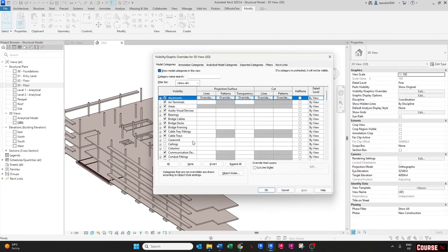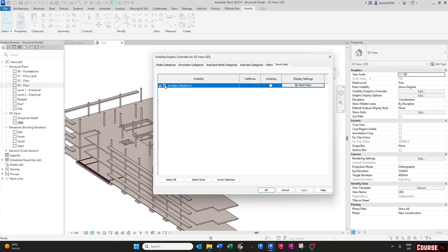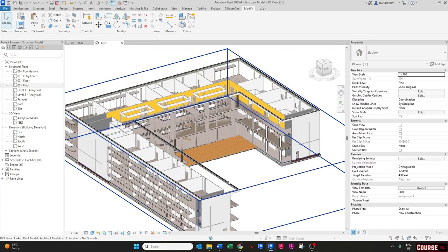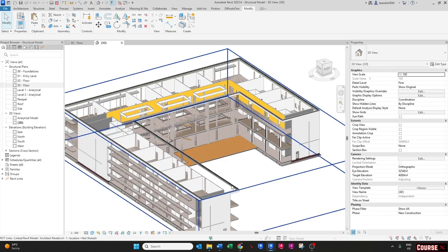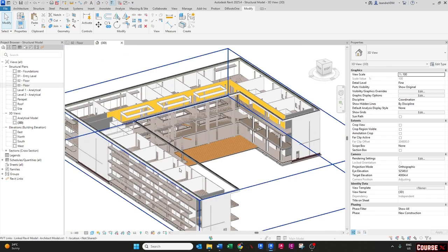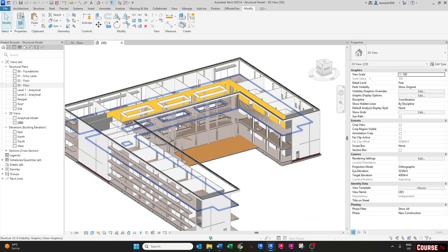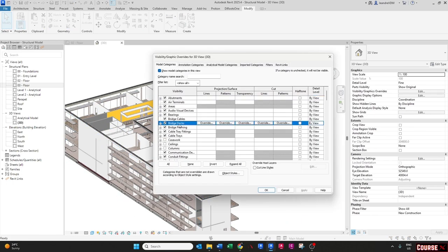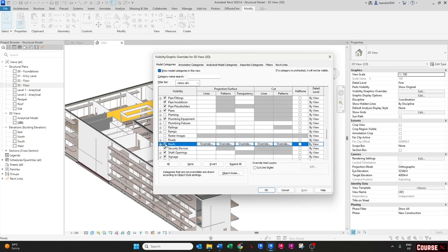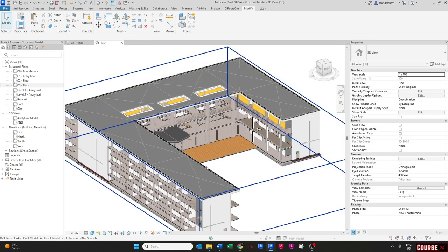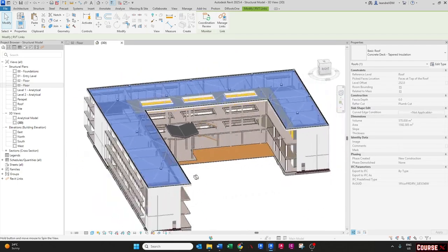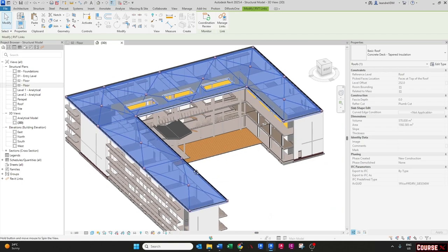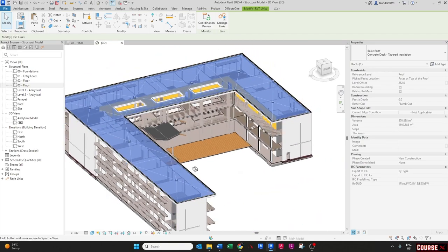Okay, so we will notice that if we switch on our architectural link again, this roof here is actually also a concrete roof, our roof slab. Because it doesn't want to copy in, since they've actually drawn it in as a roof, if you press VV on your keyboard and go to roof and we just tick that box, you can see that roof there. It says concrete deck, but it's drawn in as a normal roof sheeting roof.